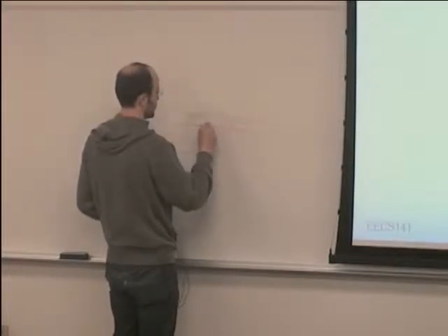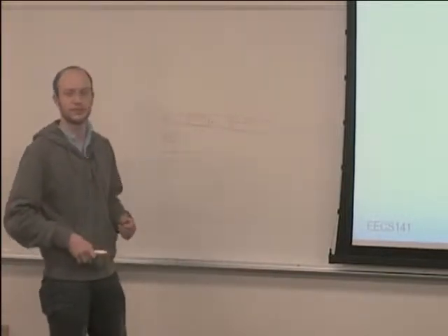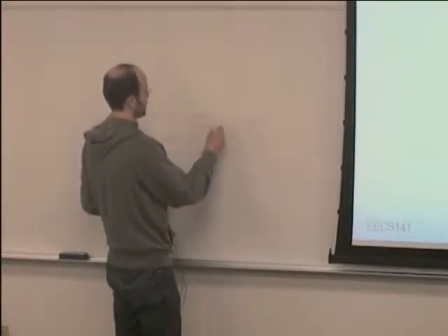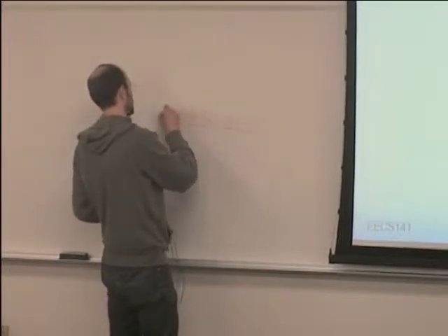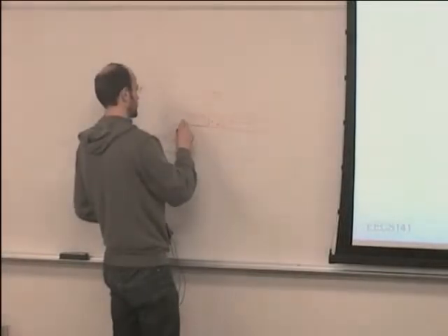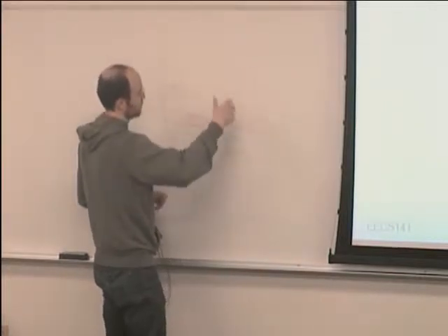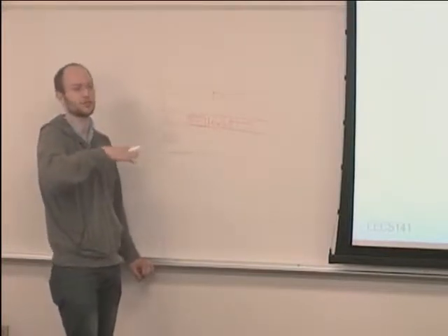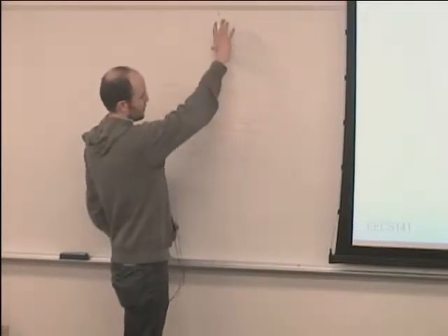some width that you can choose. It's got some thickness that is typically a process constant that you don't have any control over, other than choosing what layer it is. And then it's spaced. It could have a wire next to it. There could be another layer with another wire here. Modern processes have maybe 6 or 7 levels of metallization, maybe more, depending on what flavor it is. So you can imagine this structure repeated 9 times.